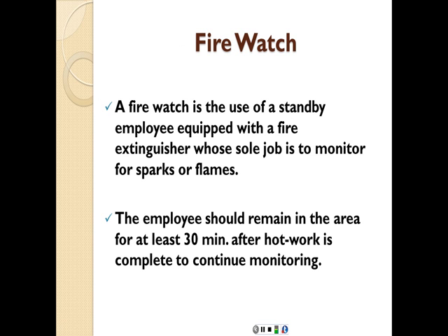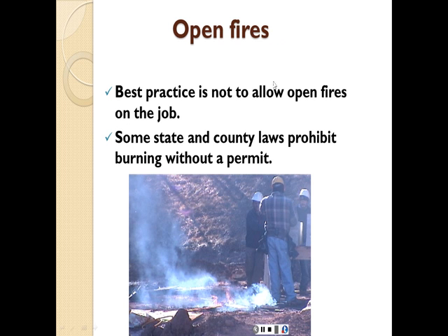The metal itself is still going to be red hot even after you stop applying the welding material to it. So you're going to keep a watch for another 30 minutes just to make sure nothing comes in touch with that hot surface, causing it to ignite that material.